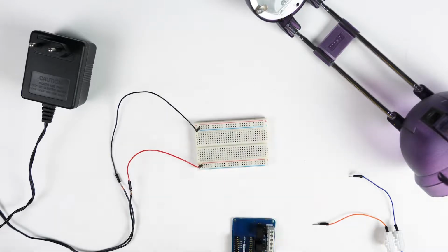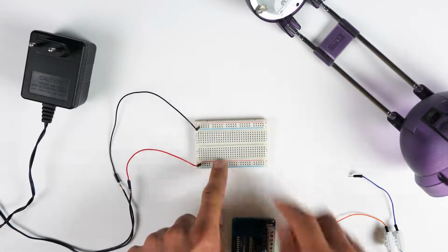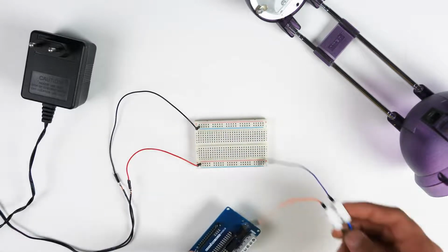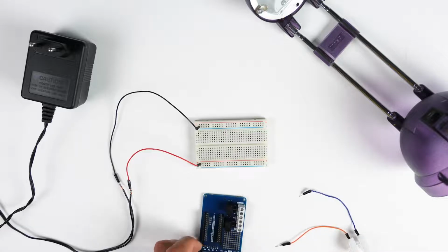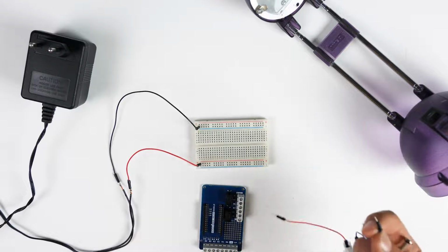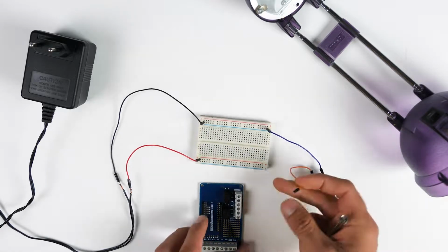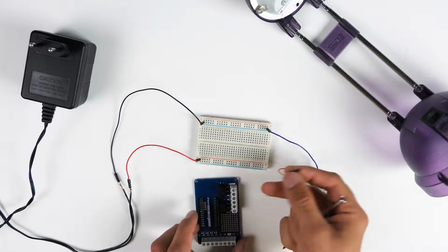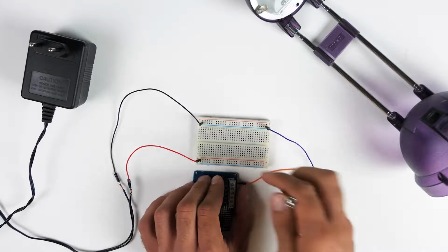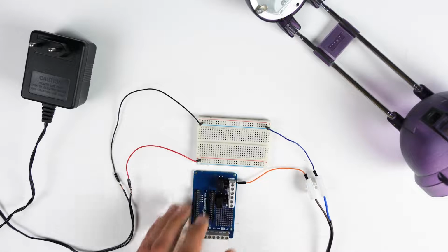And here we have the setup. So we have the power source that is connected to this breadboard, where we have the plus and the minus pole. Now we're going to connect this lamp to this relay and then to the power source. And to do this, we first need to start by connecting the ground from the lamp to the ground here, and then the power cord from the lamp we can connect to the normally closed pin. We're going to use a normally closed configuration here. Just do it like that.